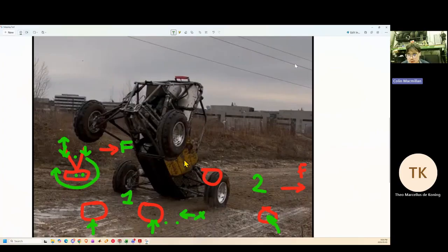The matrix multiplications, or calibrating the strain gauges? All of it: getting them calibrated, then interpreting the raw data from MATLAB or Python or whatever, and turning that into actionable decisions. Like, we have our peak strain on a certain length during a certain event. What do we do with this information now?